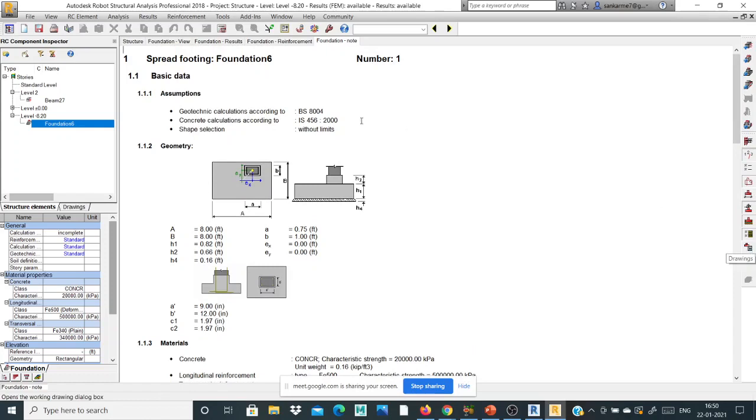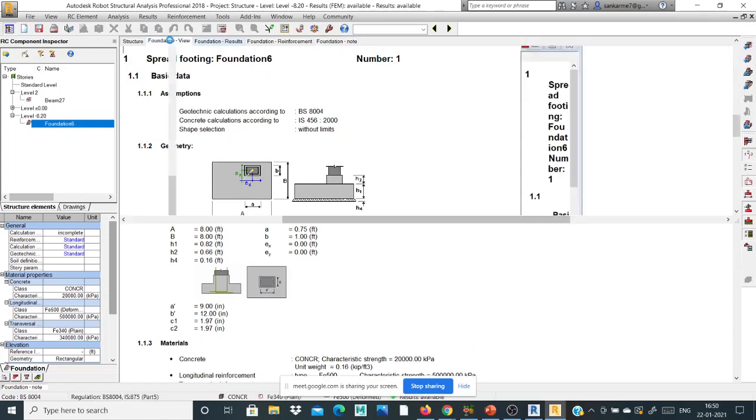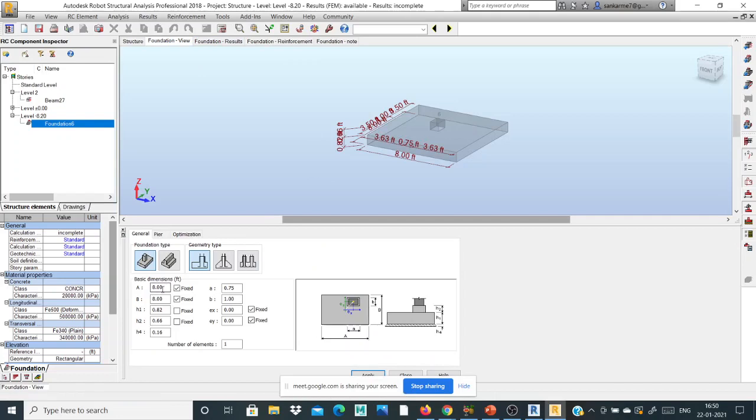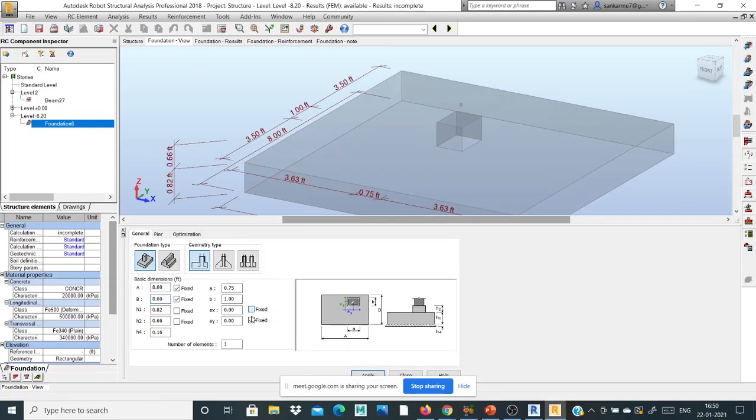And simply click drawing, and you take all the views. Once the footing fails, you change these values also, right? How do we analyze the eccentric footings? See, the eccentric directions are automatic. I take an assumption of 1 feet by 1 feet, right? I fix it and apply.